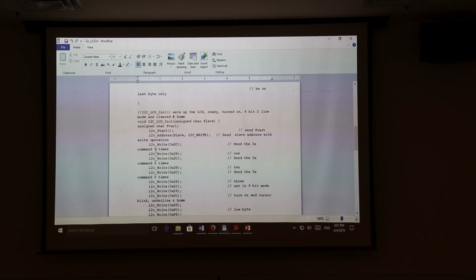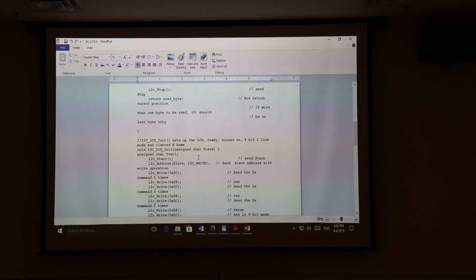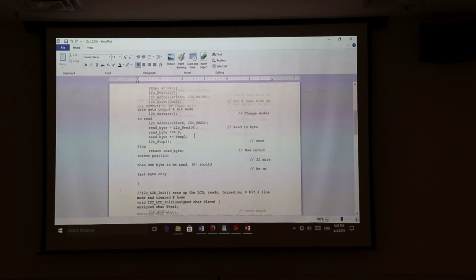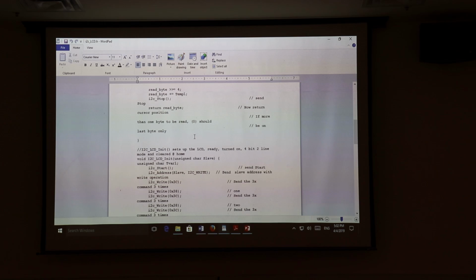And so we do have to write out the data we want to send, plus we have to leave the data in place, but toggle the bit that's actually controlling the E line. And so you have to figure out which bit's toggling the E line. And actually, I don't remember off the top of my head. I don't remember if I said that at the top. Yeah, I don't think I did. And then if you have a different one of the interfaces, now you have to use the reverse protocol where they have a different bit that controls the E line.